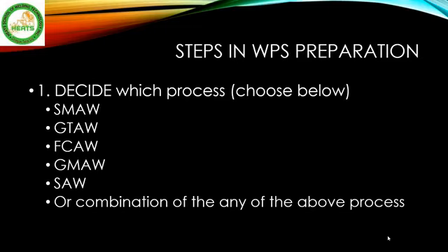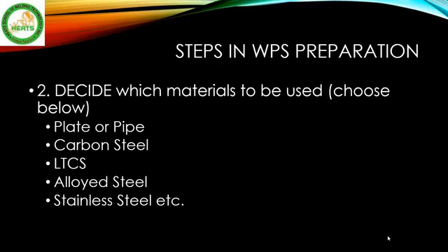It can be GTAW SMAW, GTAW FCAW, GTAW GMAW, GMAW SAW, whatever. So first and foremost, you need to decide which process you will be using.